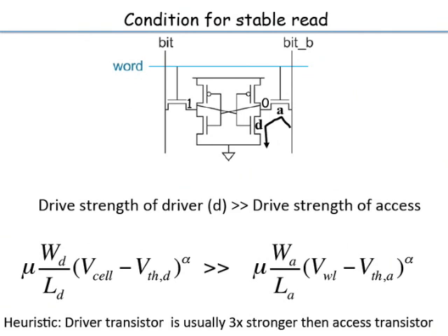And when they do the layout also, certain special exemptions are given to them so that they can squeeze the area down as much as possible. So all that is done and then it's tested out and so on, and so you have this finished SRAM cell which you use. But if you ever were to design your own SRAM cell, it might happen, maybe there are some special conditions where you have to design your own cell. Then you have to take into account all these considerations: stability during reads and writes, noise margins, and so on.